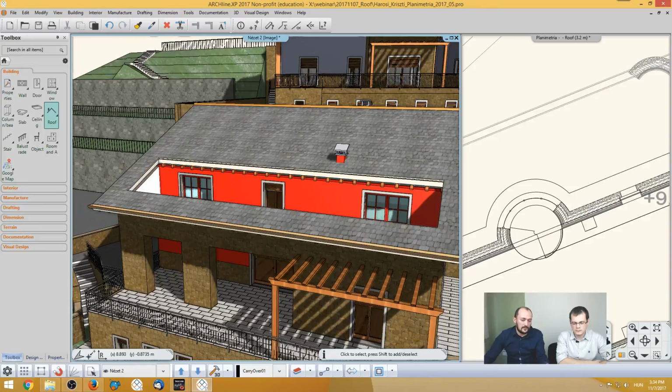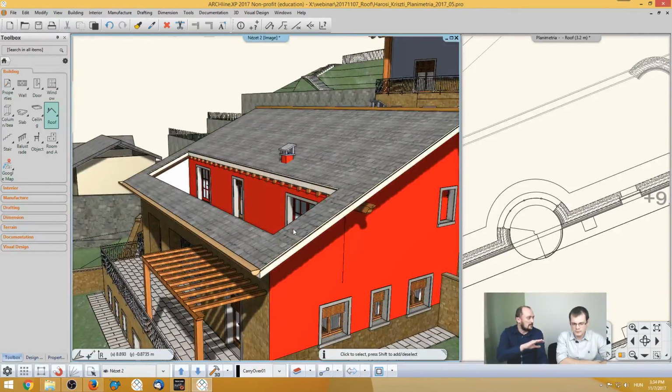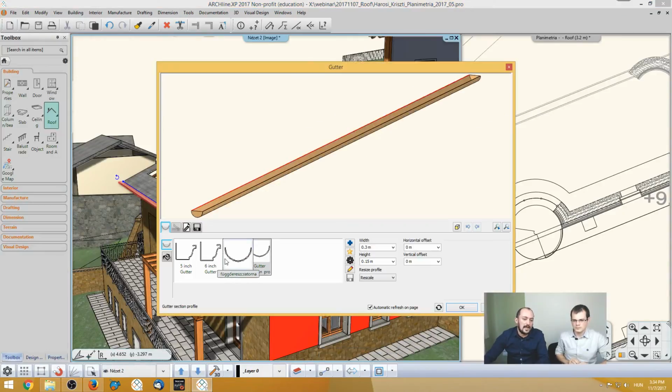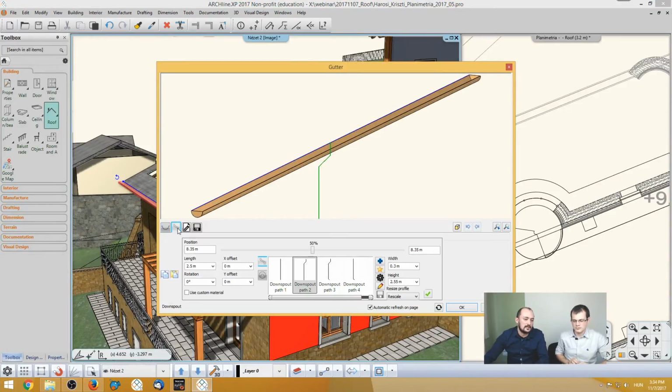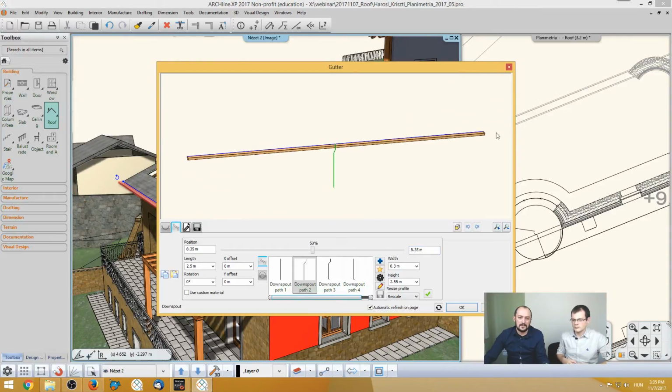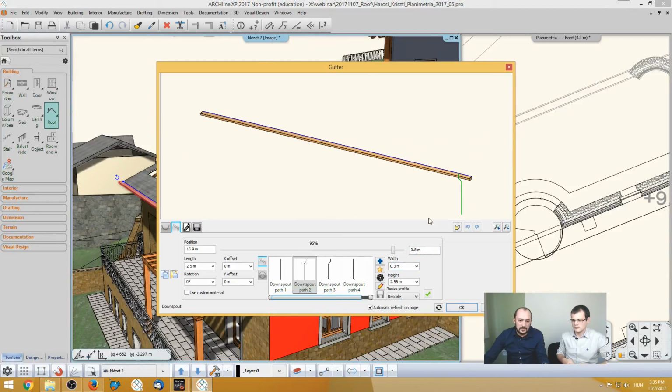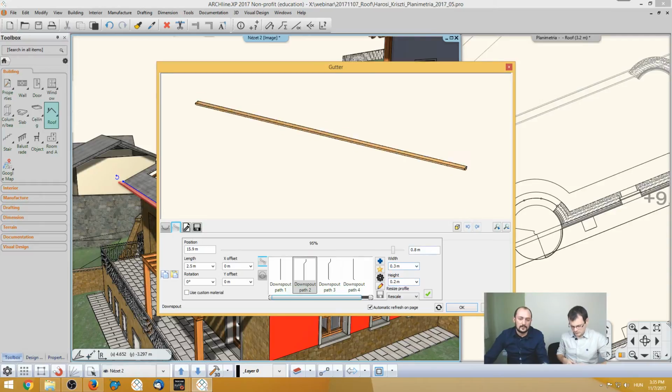See, now it is perfect. It is coming to the side of the roof. I can also change its height position to somewhere else. And of course, I can add a downspout like this here. This allows you to draft the shape of the downspout. You can also design the position of it. I think from here it will be nice to be at 0.8, yeah, and it should be, I don't know, a little bit longer, like 4 meters long, like that.